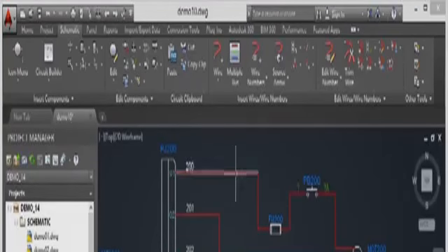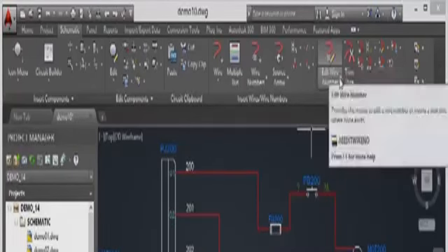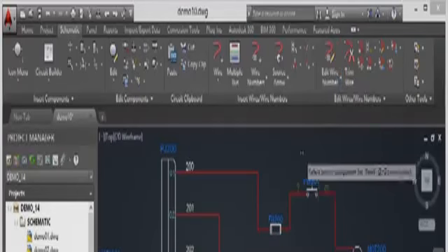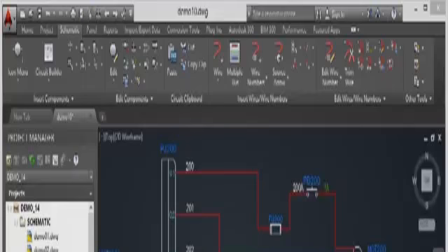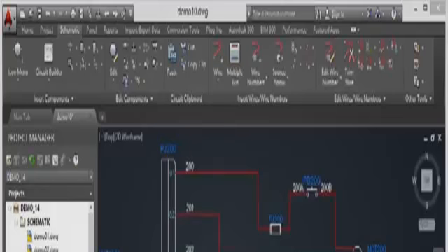Now we've got these wires here as well. So that's 200 coming up to the fuse. So this really should be 200A and 200B. Now it's already put an A there, but what I'd like to do is just renumber these. So we're going to do edit wire number here. So I'll select that one there, and that will become 200A. And you can make it fixed if you want to. So there's our 200A there. And then I'm going to select this one here and make this one 200B. So that's updated, and then enter to finish.